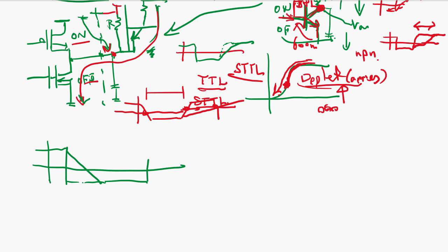And this is better than this. And this time, sometimes ringing is called ringing. This has to be controlled, because excessive ringing is going to cause noise on the IC chip, and it affects the neighbor circuit. But this is the issue in the digital circuit.